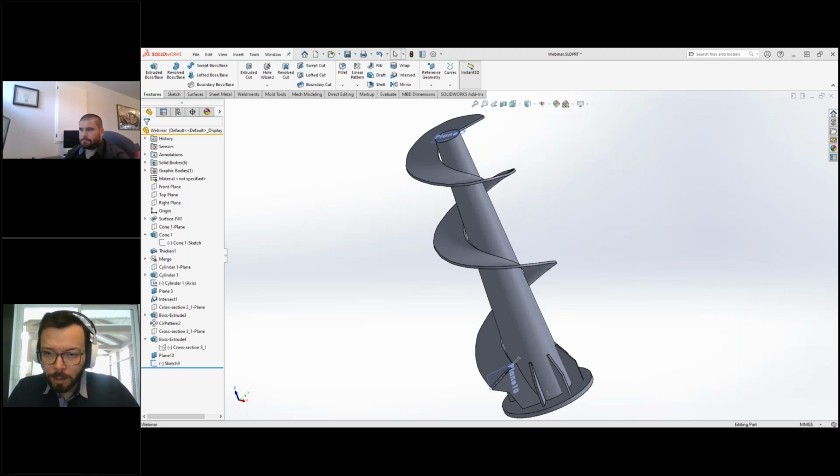Let's see. Do you need the reference dots? I could see them with the auger being scanned. You want to go ahead and answer that one? Yeah, I can answer that. You don't have to use reference targets. We call them targets, but dots or whatever you want to call them. You don't have to use them. It's just easier, especially on a big part like that and on a non-symmetrical one. I forgot what the term is in English, but the auger has the same section going all around. So the scanner needs to know where it is in space, and using just a couple of targets will help it. But no, you don't have to use targets with the Peel 3. Okay.